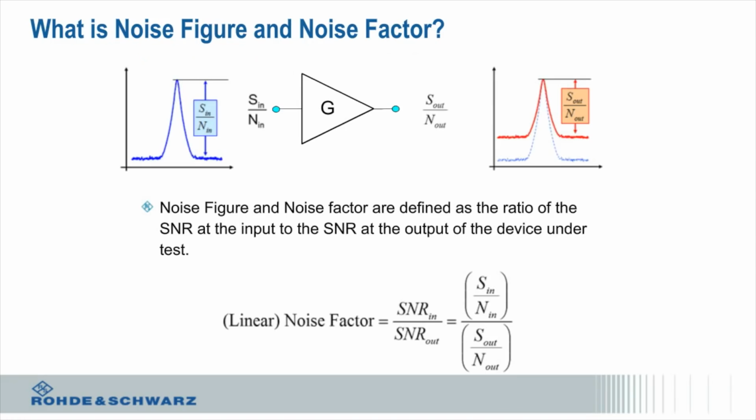So when we design a system, the key is that when you receive a signal, in an ideal world, if you look at the previous slide, my noise floor is at minus 114 dBm in that 1 megahertz channel. I don't want my system to add any more noise to that. So ideally, I'd be able to pick out a signal perhaps just slightly above that minus 114 dBm. But the reality is, if you've done engineering, you know that there's no perfect system. So when you put in an amplifier, which is typically near the front end of a system, it's going to add some noise. Anything that's an active device will add some noise.